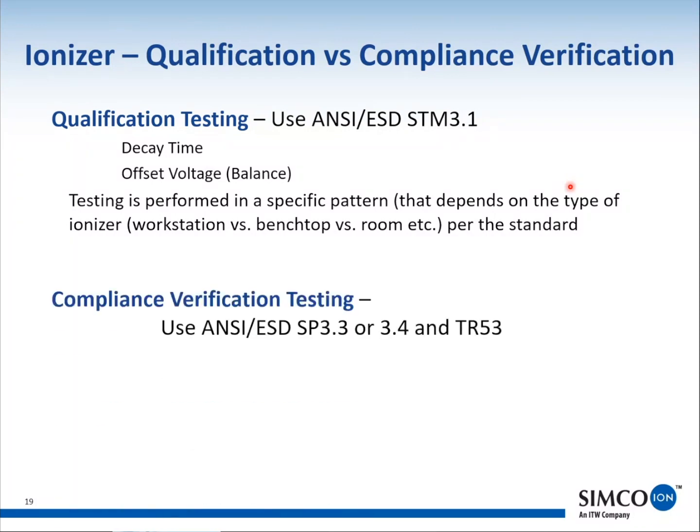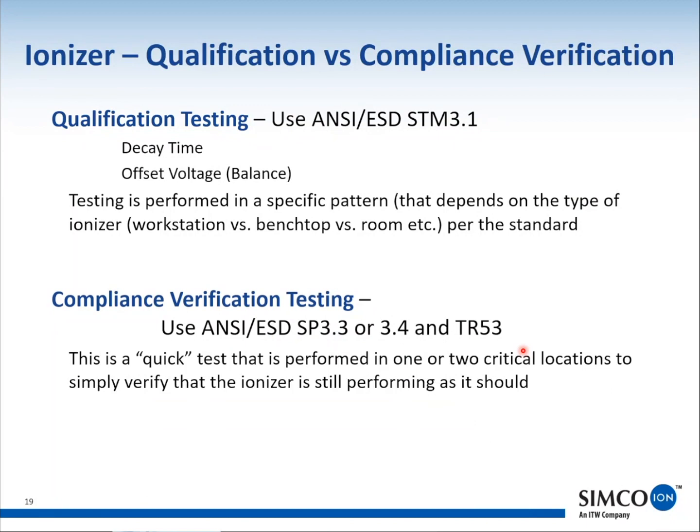Then you have compliance verification testing. There are some specific test methods for that from the ESD Association. It's a quick test that you do after the ionizer has been installed and is being operated in your workstation. You want to make sure that it's doing what you intended it to do. Just like we test wrist straps, or we use a monitor for the wrist straps, and we test grounding on a regular basis to make sure that something didn't break, we want to do that with an ionizer as well.